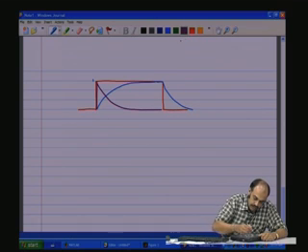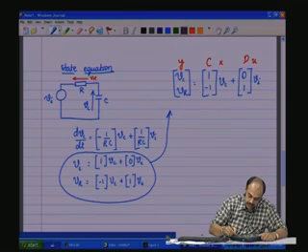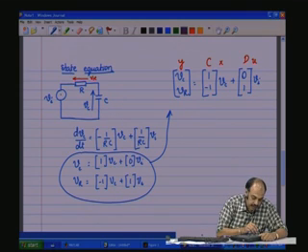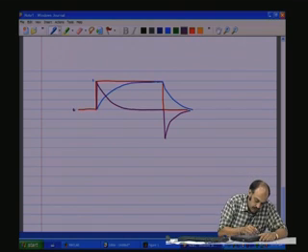And what happens to the voltage across VR? You will see that there is a reverse current. The reason being, if you look at the circuit here, the moment the input voltage is made 0, there is a charge here, this will pump a reverse current through R and the voltage across R becomes instantaneously negative. So, that is what we are seeing, it becomes instantaneously negative, and then as the charge decays, it will decay to 0. So, this is the 0 value.